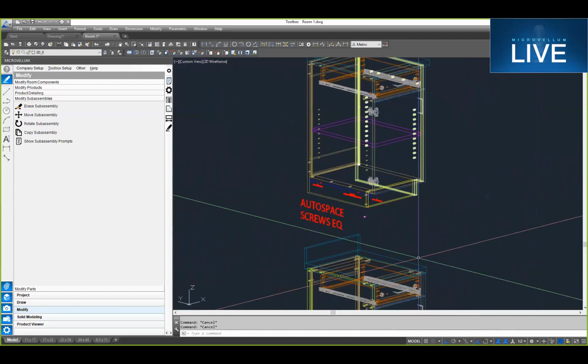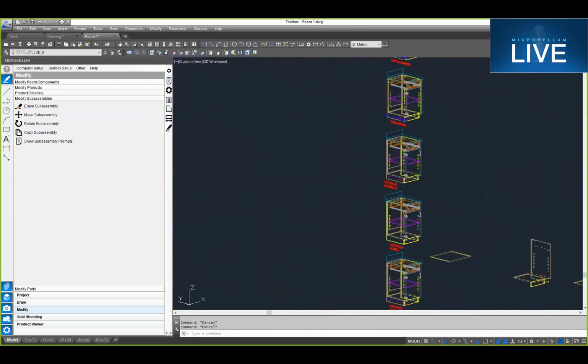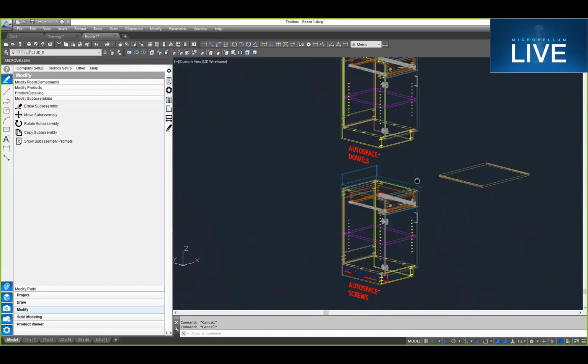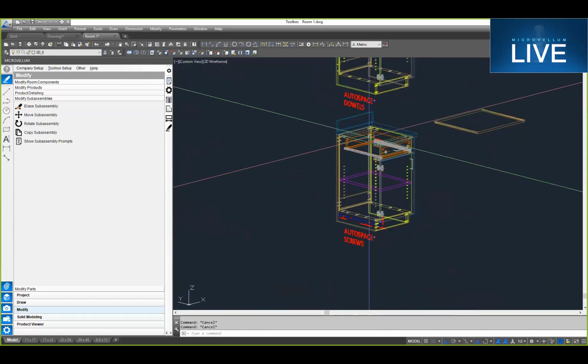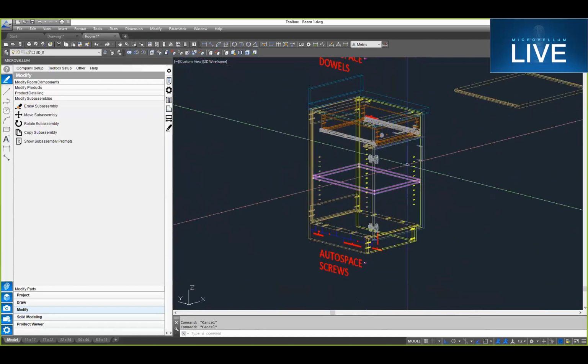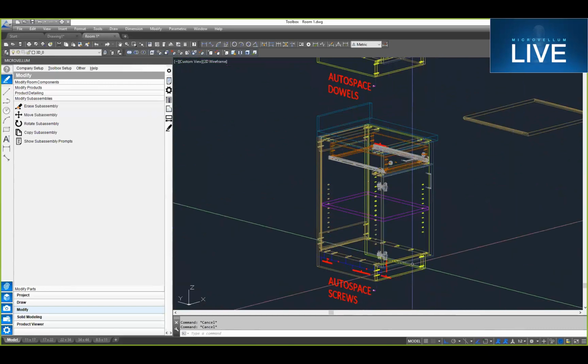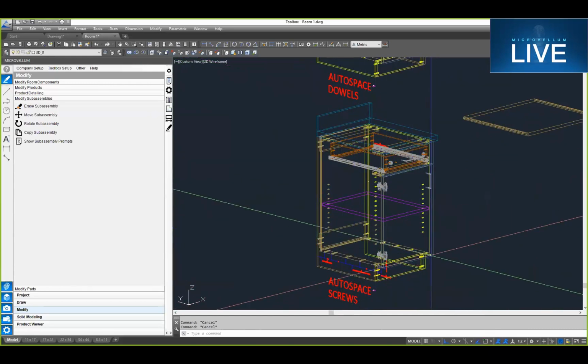But when it comes to dowel manufacturing, one of the big benefits that we talked about last week was the difference between nest-based and pod and rail-based manufacturing. With dowel manufacturing, you might be machining only the cabinet sides on the nested machine, where you're drilling some dowel holes in the face of those parts.